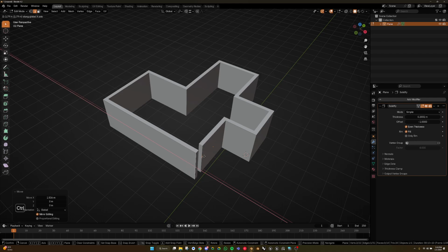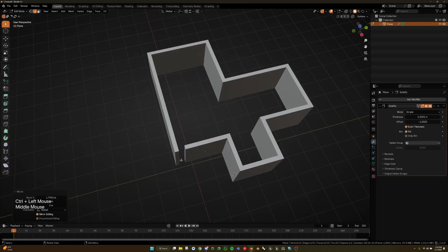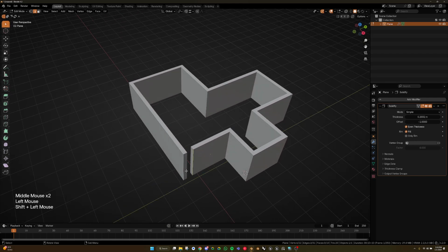You see what's happening here? You have that little icon. That means it's snapping to the edge. And that's exactly perfectly aligned with that edge. If you want to join these two, you press F, right? And that fills it in. And then you don't want this line here, so you're going to, instead of deleting the edge, which does this, you want to dissolve the edge.